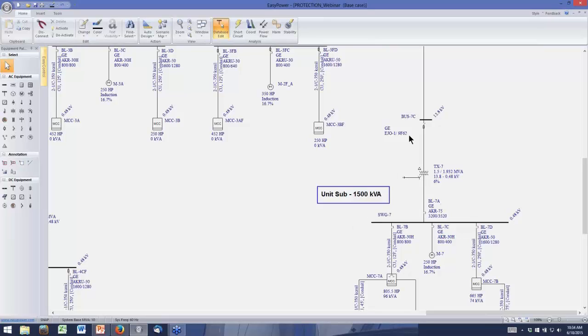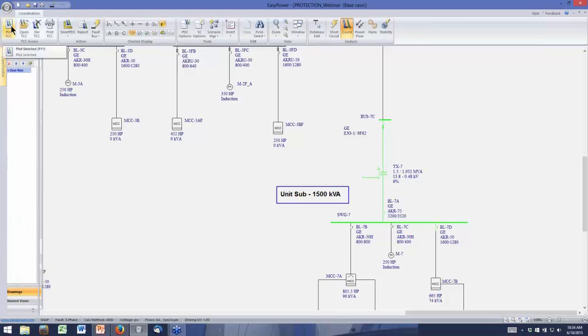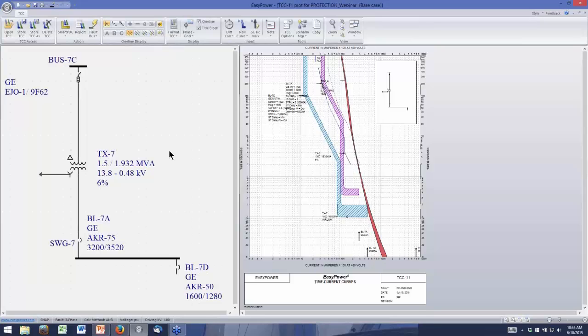Okay. So I've done that for these breakers here in this substation. So if I go back to coordination now and we take a look at this, I'll just look at one because those are basically all the same. If I go to plot, then I don't see my ground TCCs, and this confuses people sometimes. But remember just before I showed you the TCC clipping, the fact that when I do a calculation or plot a TCC, the program figures out the maximum fault current through each device and clips the curve at that maximum current.